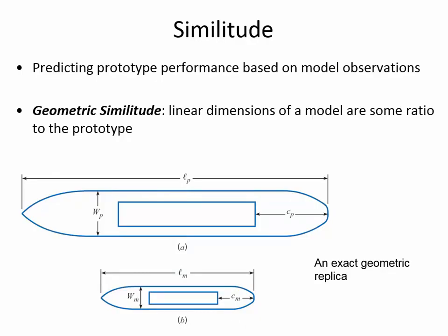They were talking about the geometric similitude of that model, how on the horizontal scale it's 1,000 to 1 and on the vertical scale it's 100 to 1. So similitude is saying that there's a relationship between the prototype and the model. In the Bay model, the prototype is the San Francisco Bay and the model is what they've got at that indoor facility. Well, we can have prototypes and models for cars, for airplanes, for boats, and one of the examples